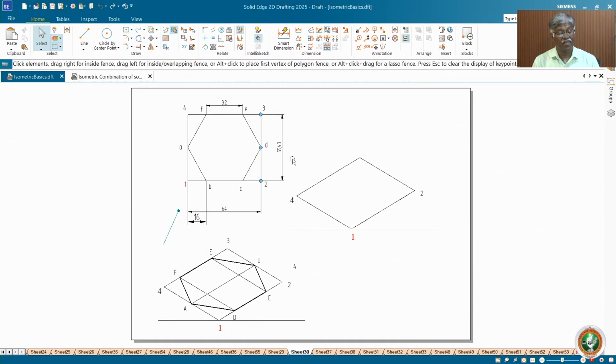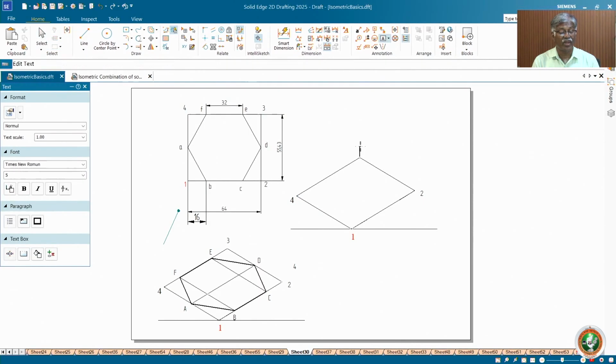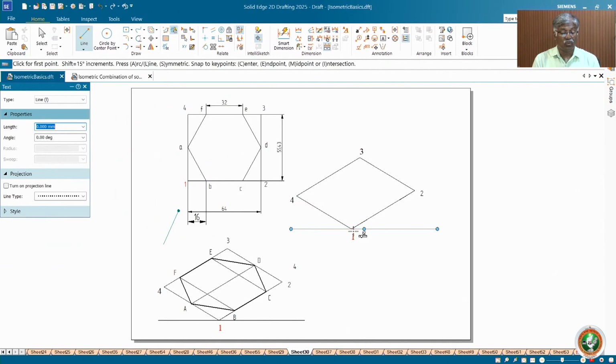It is wrong actually. Now I have here clear information that started from 1, and here is the point 3. Yes. Now between 1, 2 and 3, 4, we have to have BC and EF. So what is the distance? 16 mm from 1 or 2. Again, all are equal. So what you do is 16 mm you take from point 1 to 2, 16. Yes, confirm. Then draw parallel. That's all. You need not go for any other procedure.